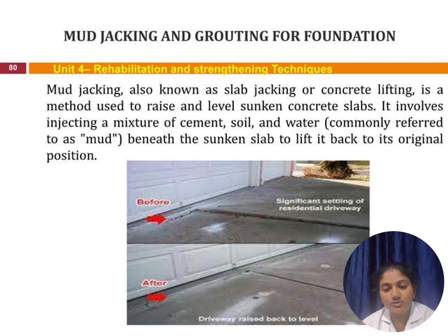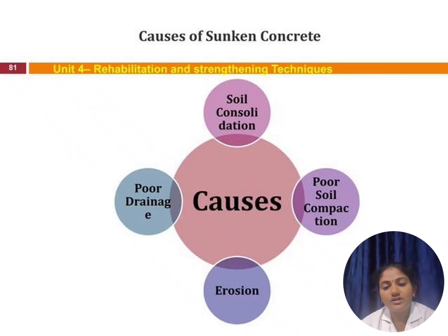And mudjacking and grouting for foundations, also known as slab jacking or concrete lifting, to raise sunken concrete slabs. It involves the injection of cement grout beneath the sunken slab to lift it back to its original position. The causes are soil consolidation, poor soil compaction, erosion, and poor drainage systems.